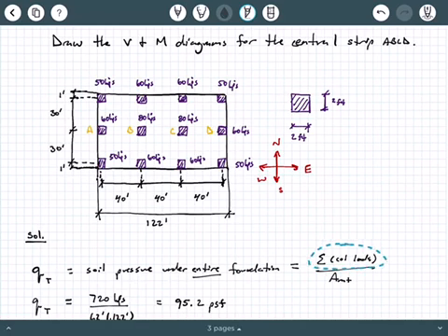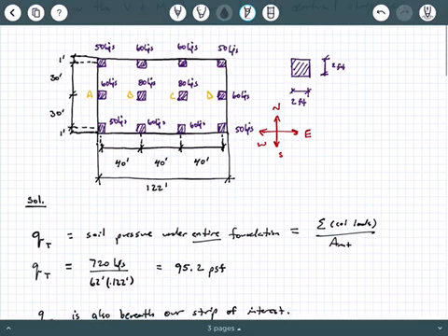So the sum of the column loads is really the sum of the factored column loads that already have LRFD factors built into them, and each of these column loads is already based on a critical LRFD load combination. So it's not really the weight of the building, it's more than that, because you factored in other things, maybe live load, maybe rain, etc. So it's the sum of all these column loads divided by the total area of the mat.